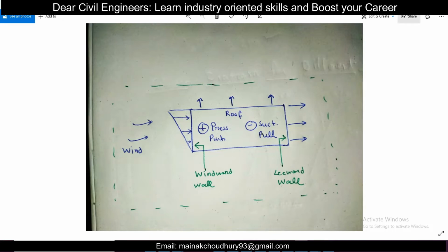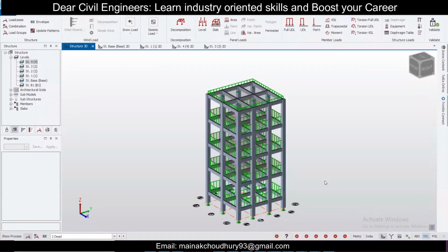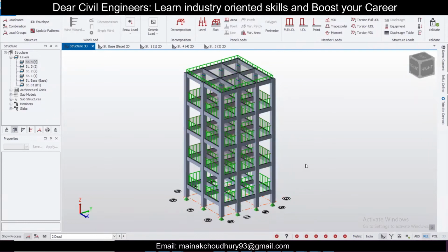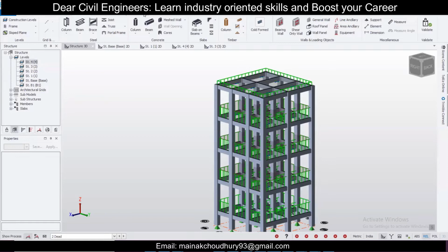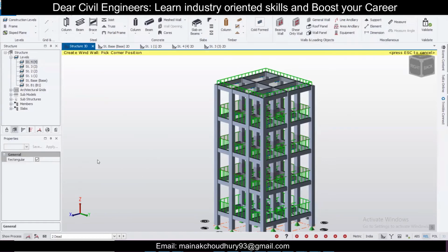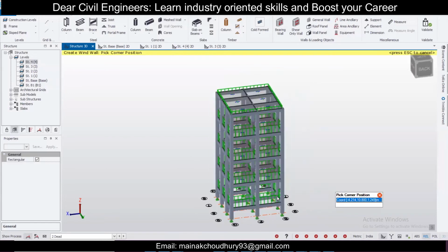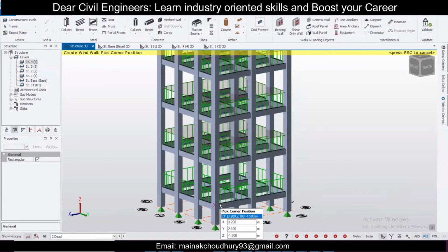You're going to remember that, and all the other details I've explained in the ETABS videos or the IS code part. You can just go through that. In the 3D view, we'll go to our model and make our wall panels. Rectangular panels have been selected. Right click and obtain a suitable location for selecting.